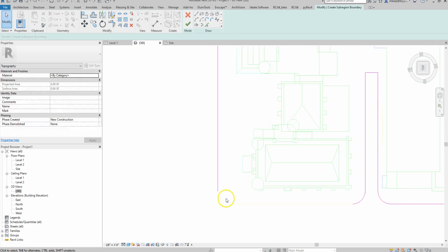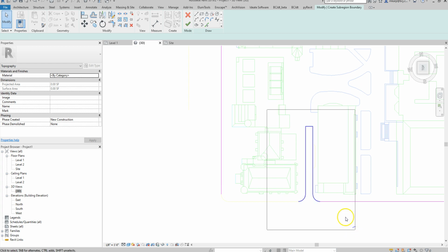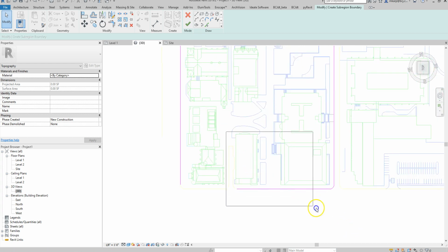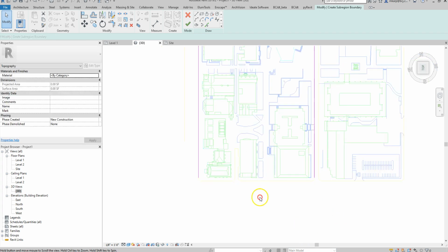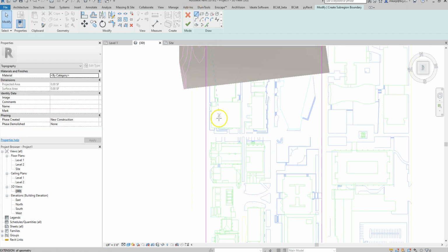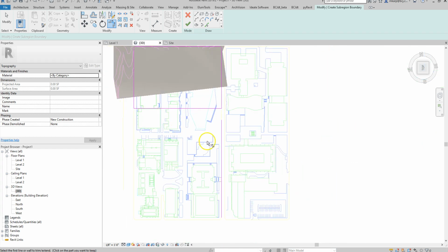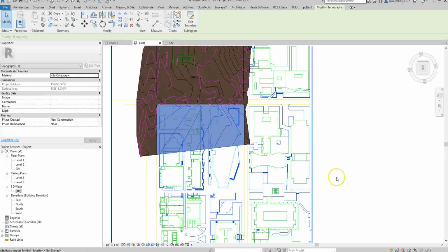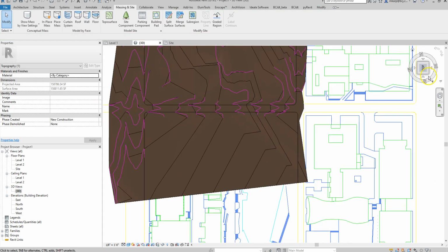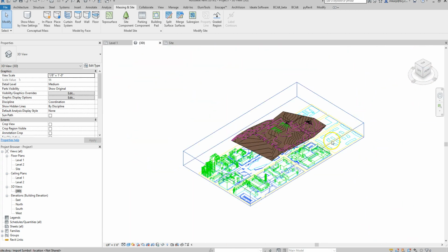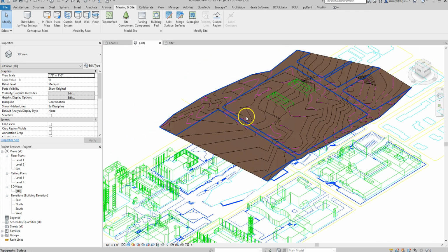All right, I'm going to delete all those lines out because we don't need any of this. Since we're only intersecting with our site there, I'm just going to make an intersection here. And we'll use the trim command, which is this command. It works exactly the opposite of AutoCAD in that you click on the lines you want to keep instead of the lines you want to delete. See if it's any better. That's better. All right. So that took a little while, but this is always long whenever we're trying to make one of these pieces of topography.